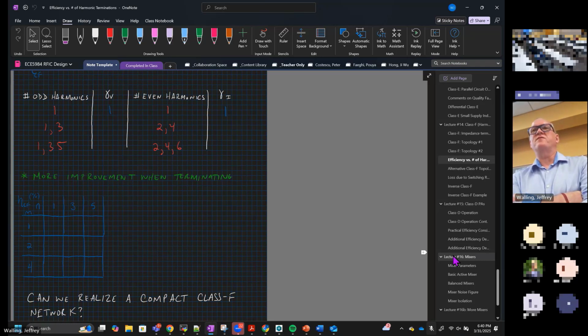In any real power amplifier, you're going to have matching network losses, current division, all those negative things. So if you design the power cell to just barely provide a quarter of a watt, which is 24 dBm, you're probably going to have a very hard time actually achieving 24 dBm because you have all these losses you didn't account for when you sized the device.